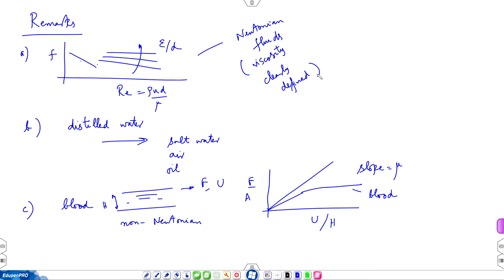So, that is how the data generated on a lab scale is used for, let us say, finding the pumping effort for drawing water from a well or power output of a turbine. In all those problems, we use the same Moody's diagram, because as long as we match the Reynolds number and the surface roughness, we can get the friction factor.